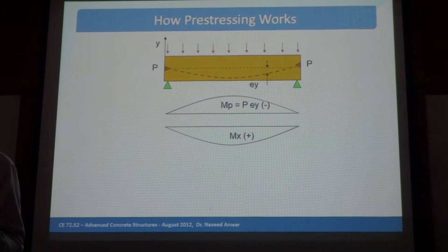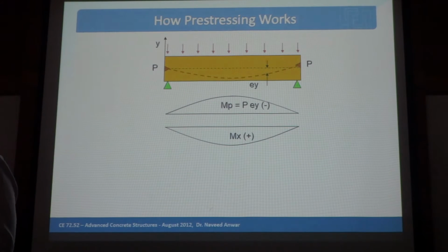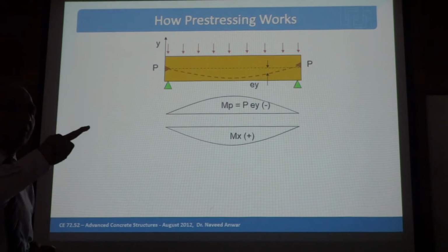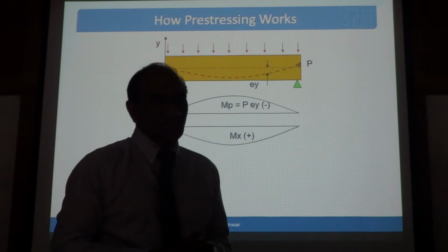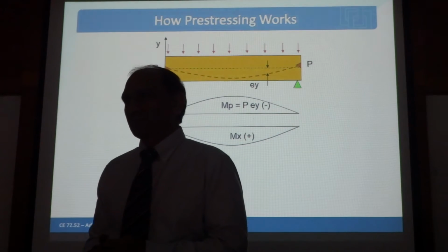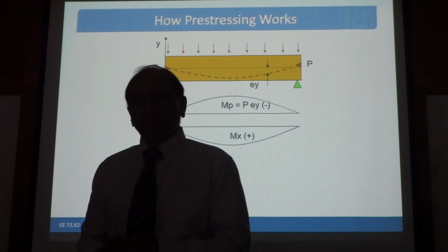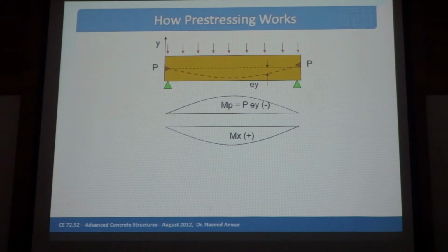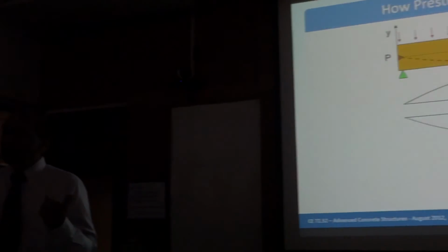And what about earthquake? Which basically means we can never balance all the loads, because one tendon profile can only balance one load condition, not more than one. Correct? So that is why pre-stressing can never be 100% stress-free, because some load condition, some load case will always not match with the original pattern.